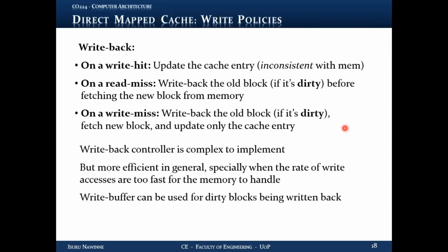It becomes very efficient. Write back caches are quite efficient. And again, you can use the write buffer to send these evicted dirty blocks, written back to the memory. In the event where a lot of blocks may be replaced in quick succession due to the nature of your program, if you have a write buffer, then those bursts of write backs to the memory can be sent through the write buffer, and the CPU doesn't have to be stalled.